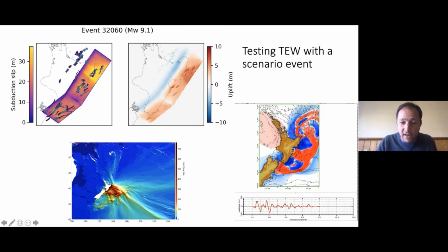On the right-hand side is a vertical deformation model. So if you take this distribution, or the amount that the land has actually moved, you can turn it into an approximation of how much the ground surface moved up or down. So that's what I'm showing you here. After this big earthquake, the ground in red was elevated, was uplifted, the ground in blue subsided or downdropped.